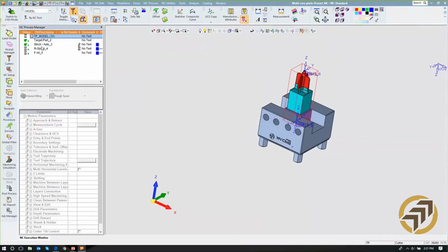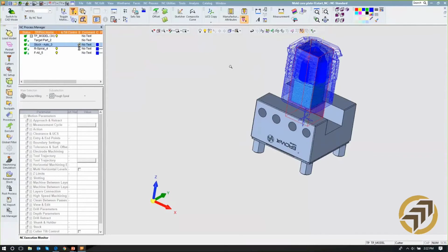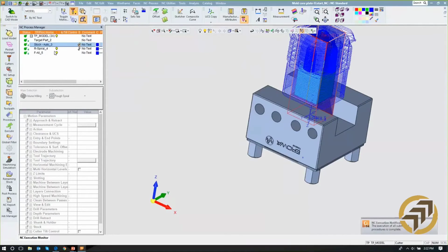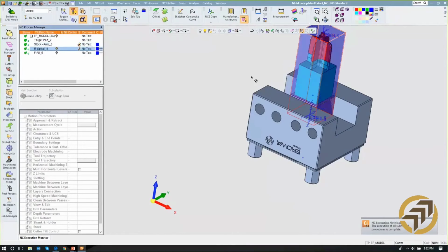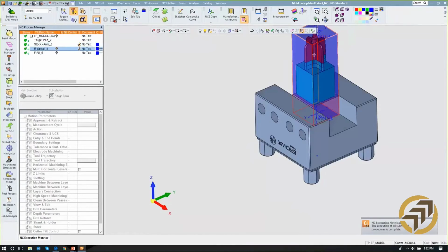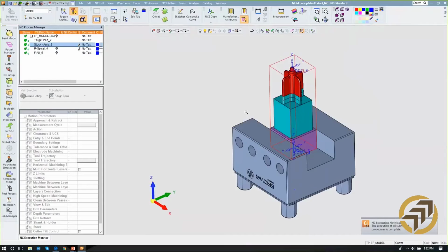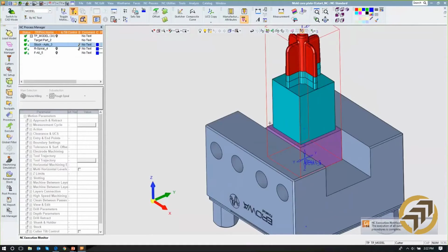I'm creating a stock model that looks like this. You notice that you can be specific. I'm grabbing just the graphite, and it's smart enough that I can program how I want it to see what that graphite looks like. It's a nice thing that I can step into it and say, I want you to grab just the light blue cyan colors and the red faces, and we want that to be what we call the graphite, and then ignore the purple and the gray.